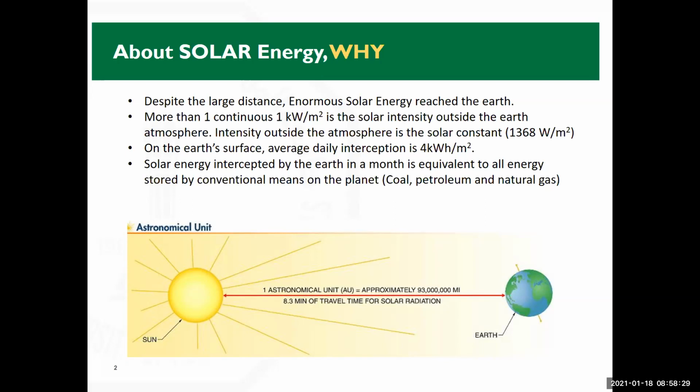And by the way, this value is not a sacred value. It's not strictly constant. It's almost constant; although they call it the solar constant, evaluating this value has changed from one source to the other. Some scientists said that the value of the solar constant is 1,365. Some said, no, it's 1,342. So this kind of variation is within a very small percentage, and in this course, in this book, we are going to consider it as 1,368 watts per meter square.